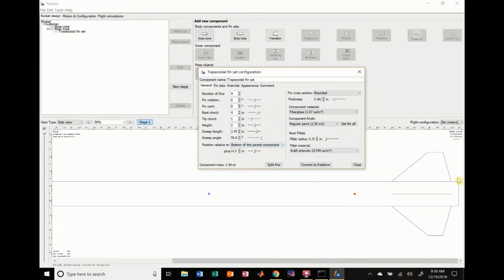So everything's changed on here. These fins look pretty good. And another thing we typically do is we try to shift the fins, the sweep angle in the back. We try to shift that forward instead of having it basically vertical or coming back off the edge like this. Because again, those fins might impact first, but if you shift your fins forward or sweep them forward like this, they might not strike the ground first. It might hit this bottom portion of the rocket first before impacting one of these fins. So you don't really want to lose one of your fins because it's a big pain in the butt to deal with. So we have those fins attached there.